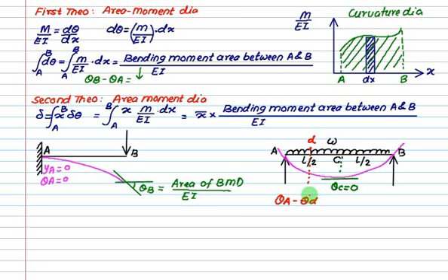For that, you have to draw your loading first. Then guess what the deflection is. The guess can be made very well. If the load is downward, naturally the deflection is also downward. And where there is a support, there is no deflection. Everybody knows this. So in the case of a simply supported beam, the maximum bending will occur at the center.